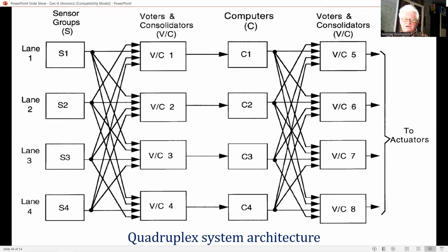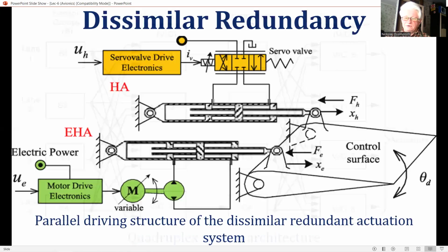The essential buffering and isolation of outputs, like electro-optic isolators, is omitted for clarity, but is essential to prevent electrical faults in one channel propagating into another. For common mode failures, first, use two or more different types of microprocessors with dissimilar software.